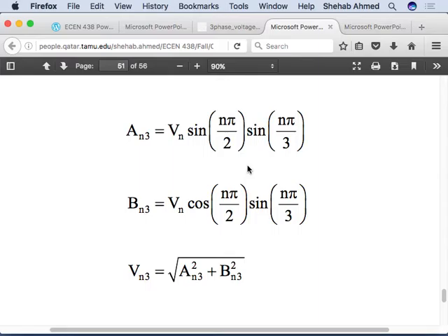So power system studies, people that took 459, we conducted a load flow study. A load flow study is one of the studies that you typically conduct for a power system. You want to know the rating of equipment. So you conduct a load flow. Okay, you want to know if when the motors start and suck a huge amount of current, motor starting is, induction motors start with a high current. So what happens when you have high currents for a short period of time? High currents means big voltage drops. Big voltage drops correspond to low voltages on equipment in your power system. Can your equipment operate safely with a low voltage? You have to conduct that study. So that's another kind of study that you conduct in a power system.